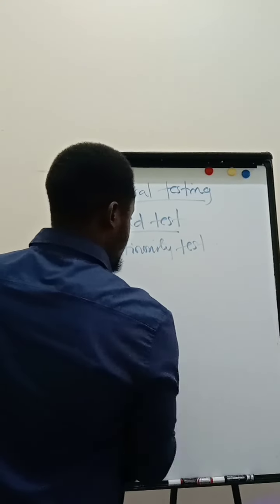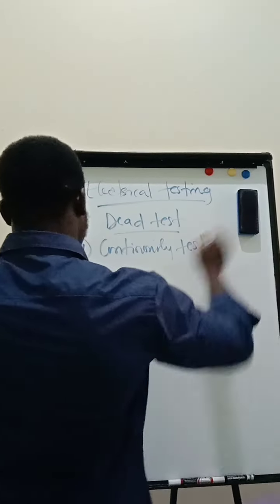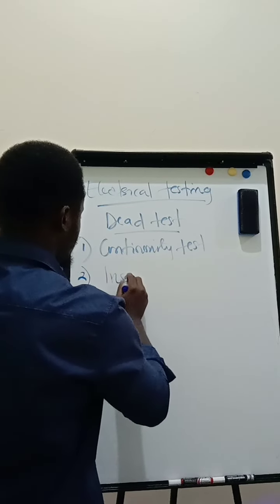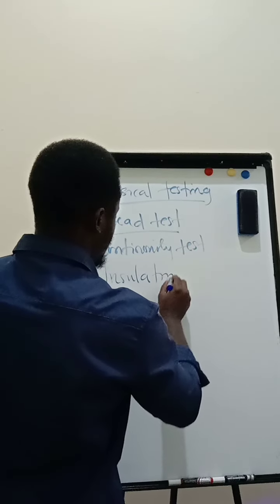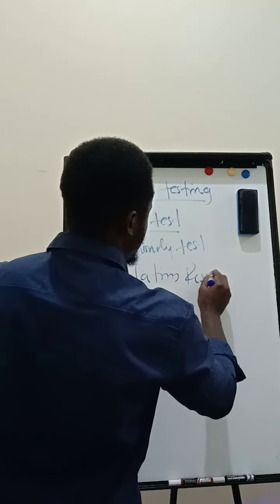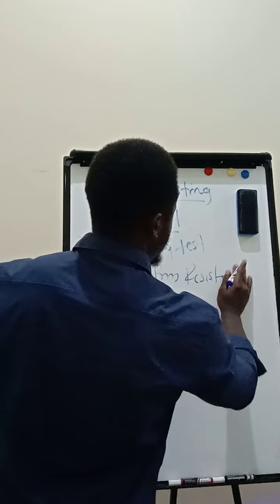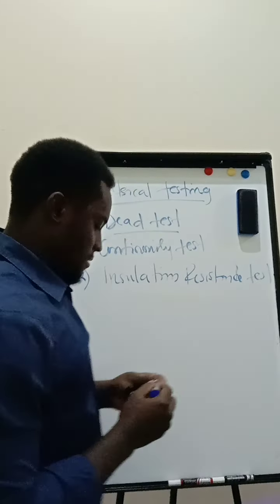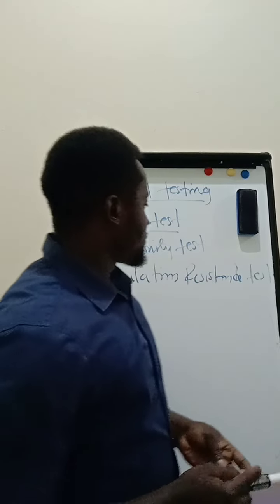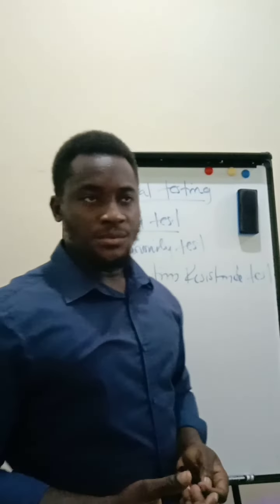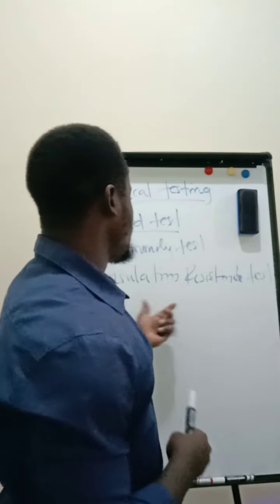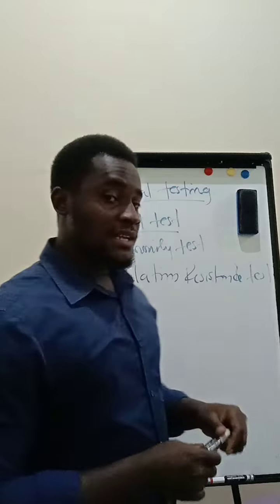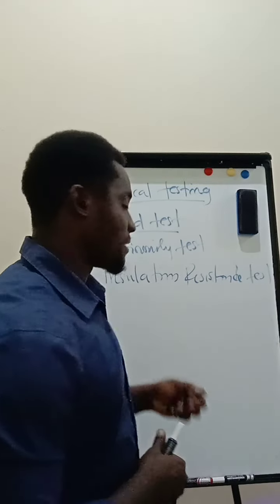So the next test, as per BS 7671, will be the insulation resistance test. The insulation resistance test should be carried out to ensure that we will not have any joint between two different conductors of different polarities, and we should have a standard value which should not be less than 1 mega ohm.